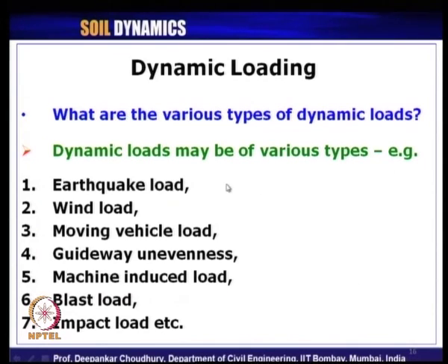For example, earthquake load is a dynamic load because this load varies with respect to time. Wind load is also a dynamic load because here also it varies with respect to time. Moving vehicle load, when any vehicle moves on any road, bridges, etc., that load is nothing but a dynamic load.